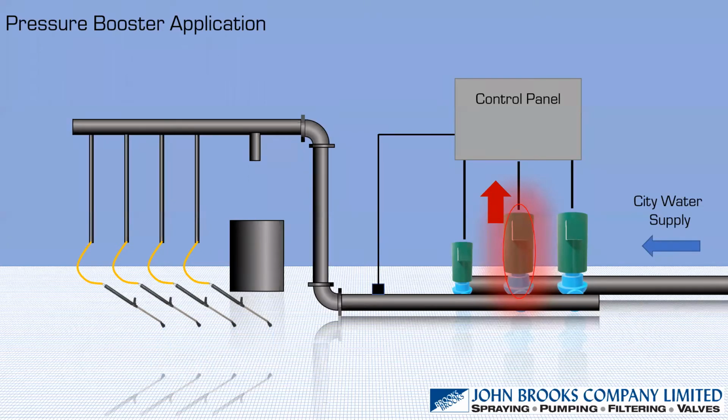In some positive displacement pump applications, if they don't have VFDs, there's a pressure relief valve or regulating valve. And instead of varying the speed of the pump, the regulating valve just dumps the excess flow back to the suction. And that really wastes quite a bit of energy because we're pumping that water for nothing, just sending it back to the supply tank. And it can also cause problems with overheating the water because the water heats up every time it goes through that pump. So VFDs are certainly, in my mind, a better solution for this application. Sure. Yeah, you're only operating the pump where it needs to operate. You're not over operating and then bypassing.